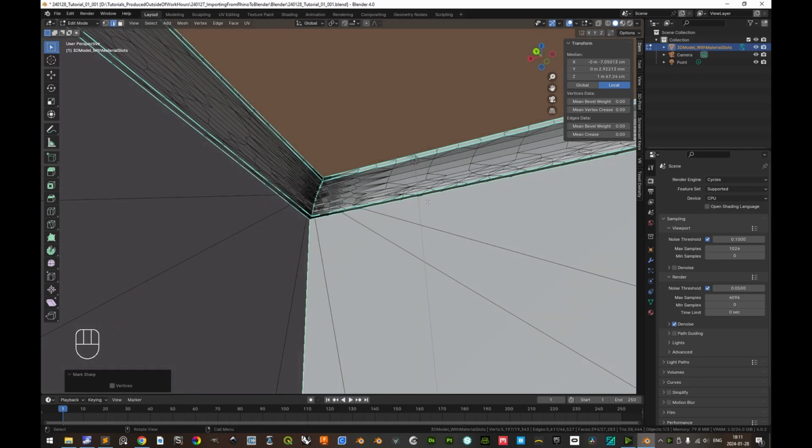As such, it is good procedure to also mark these sharp edges as seams. A UV seam will, when the mesh is unwrapped, necessarily increase the number of vertices the render engine will interpret as separate, but if it is already marked as sharp, there is no additional performance cost for marking it as a UV seam, and in this case it will be easier to unwrap the mesh.